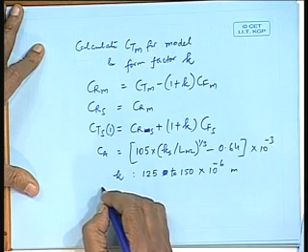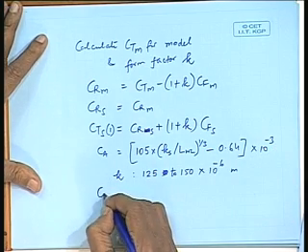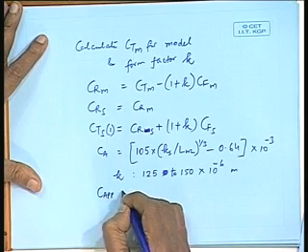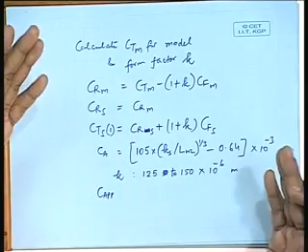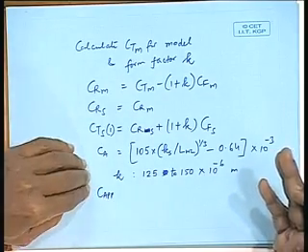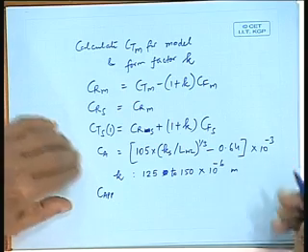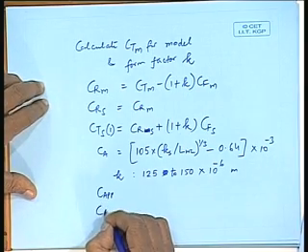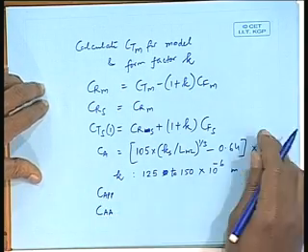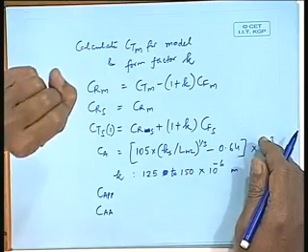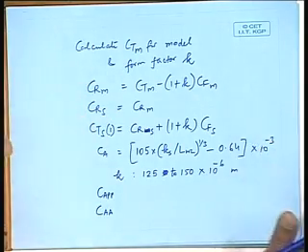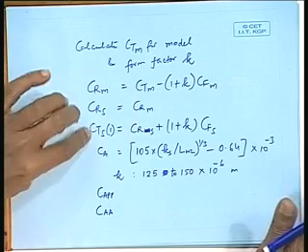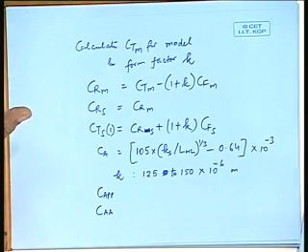Then we have the appendage resistance. You have to calculate the appendage resistance and convert it to a coefficient, so that you can add it to CT. Similarly you have to have the wind resistance coefficient. Again calculate the total wind resistance, divide by half rho S V square, the way CT is calculated.